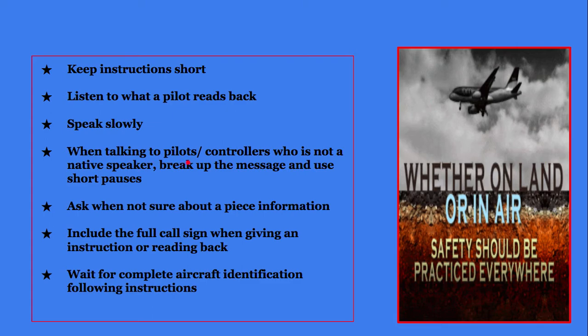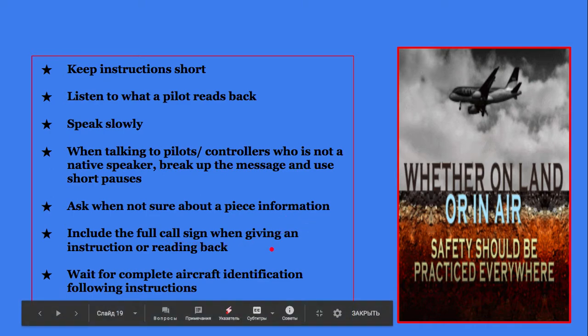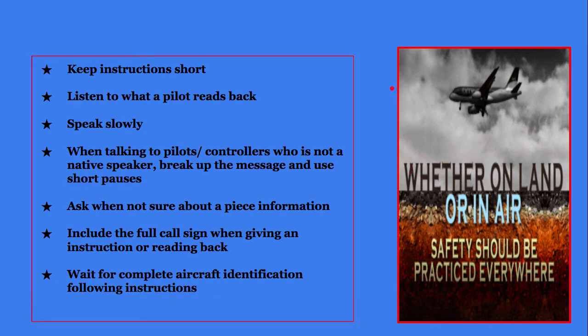When talking to pilots or controllers who are not native speakers, break up the message and use short pauses. Ask when you're not sure about a piece of information. Include the full call sign when giving an instruction or reading back. Wait for complete aircraft identification following instructions. And there is a statement: whether on land or in air, safety should be practiced everywhere.